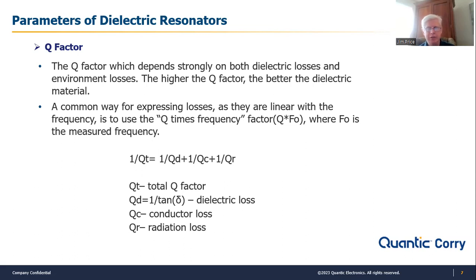In a lot of cases, that's a good thing, because to get fairly narrow band in like that 1 or 2% in a normal metal resonator, or even a waveguide filter, you can a lot of times have a lot of insertion loss. And with dielectric resonator filters, you don't really get that high insertion loss when you have narrow bandwidth. They love operating in that environment, actually.